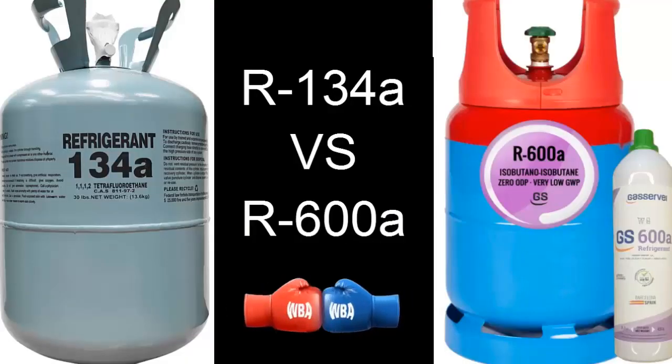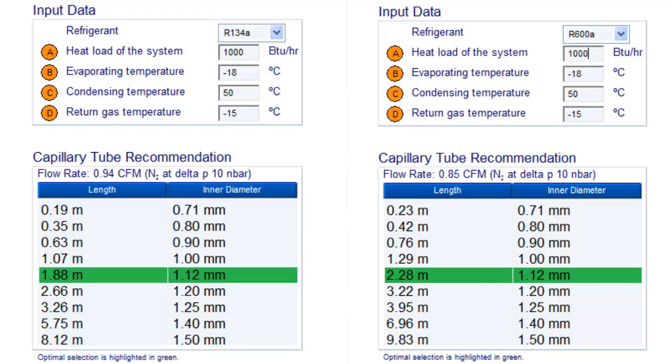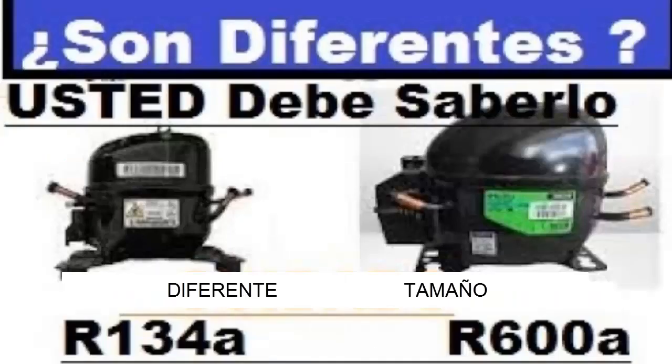R600a has proven to reduce the energy consumption of refrigeration systems compared to R134a. R600a and R134a are not direct substitutes for each other in equipment that has already been used, unless authorized by the manufacturer. However, if R600a is replaced by R134a, the capillary must be changed, because the displacement of the compressor with R600a is higher than with R134a.